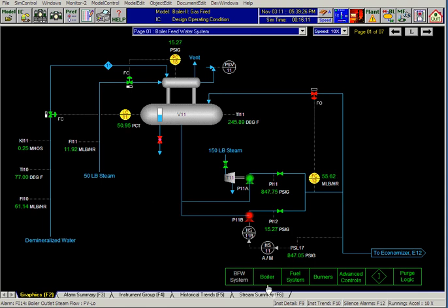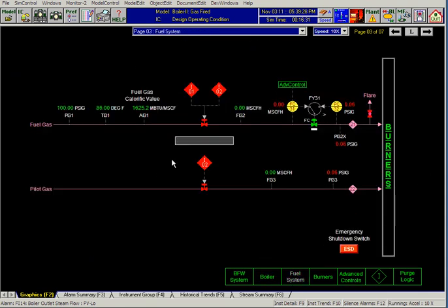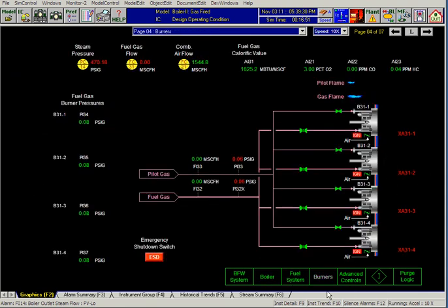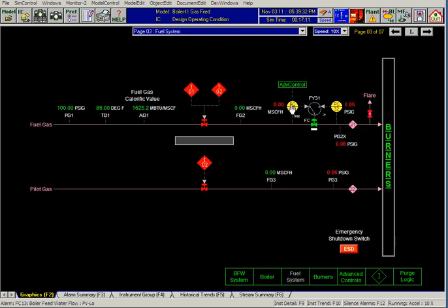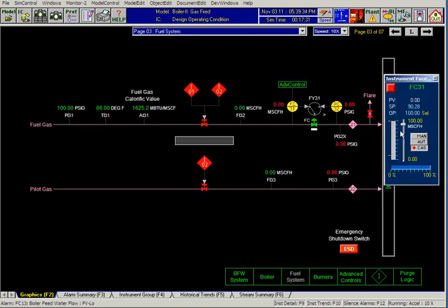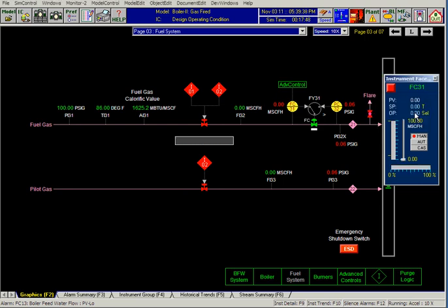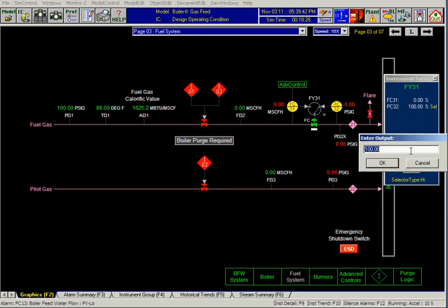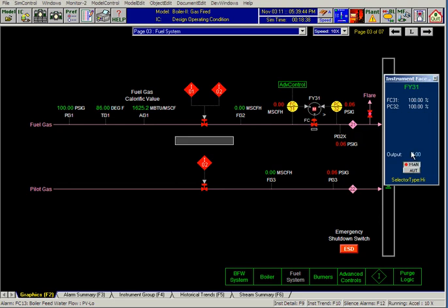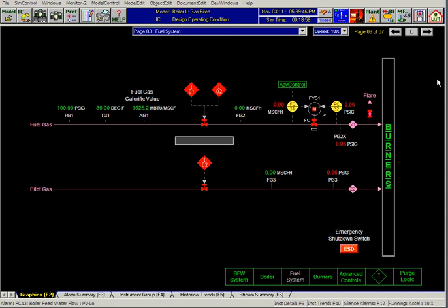Once the boiler trips, we got to bring it to the safe condition. We need to quickly come to the control valves, maybe set them in manual mode. In real life, probably the valves automatically go to manual mode. Now, maybe it is written based on a program in DCS. Here you do everything manually. Goal is to learn.